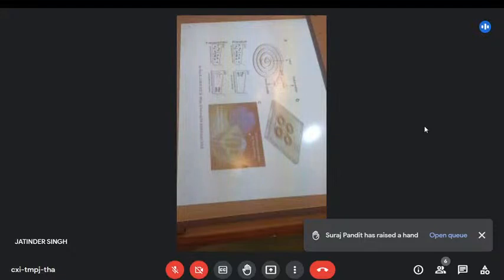Centrifugal devices also have been routinely applied to blood product separations. So there's a couple of blood cells, white blood cells that are used for therapeutic purposes. I think they're the T4 helper cells. These are isolated as well using these kind of devices. Because it's very mild, there's no significant shear stresses. A lot of cells don't like filtering because they don't like being squashed to a filter in a really high flow rate environment.